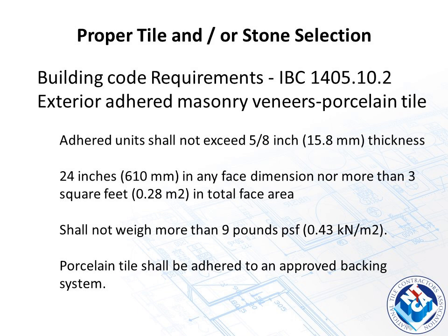So the unfortunate part is if we go to the code change meeting, which I'm pretty sure is this year, it'll still take a couple of years to get it implemented. Then of course, once the codes come out, they aren't automatically adopted by most cities, so they have to be adopted by the area. So we are definitely going for larger format tiles, up to 4 foot by 4 foot, and in some cases, as I said, 1 meter by 3 meters. So that is being submitted to the IBC, or ICC, this year.